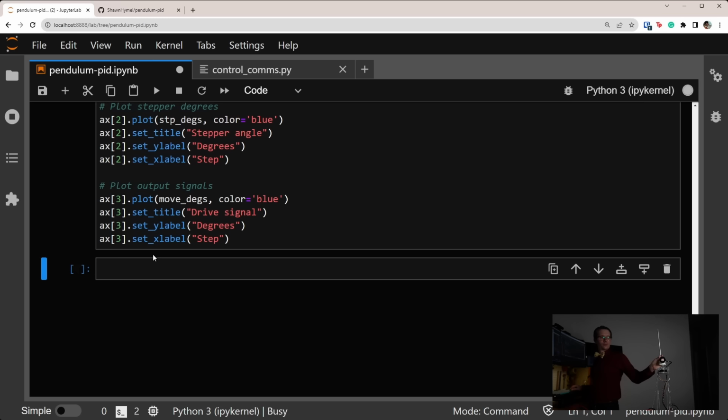It should get up to max speed very quickly. I've set the maximum speed to 5,000, which is about half of their maximum. That seems to be a good compromise between giving me a very high speed that can correct for a 10-degree offset from vertical, while not being very jittery in its motion. So you want to find that balance. I played with these parameters to find a good balance. Note that this can take some time, and I was just doing this by feel before moving on and tuning the PID controller.